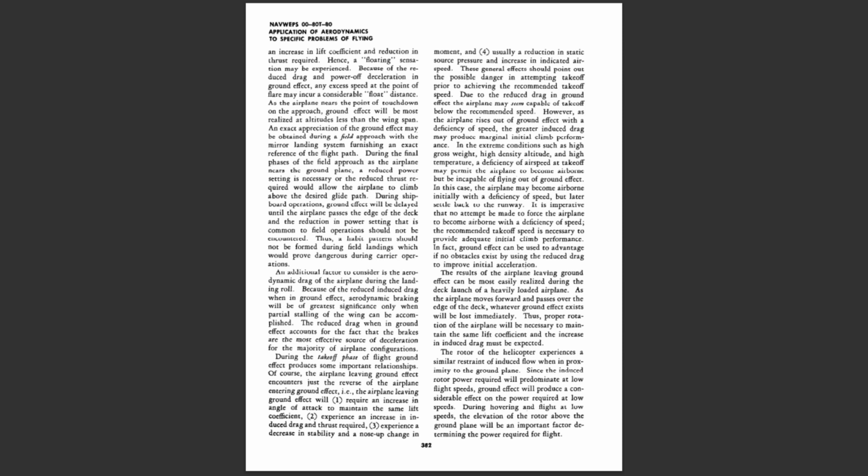During the takeoff phase of flight, ground effect produces some important relationships. Of course, the airplane leaving ground effect encounters just the reverse of the airplane entering ground effect, i.e., the airplane leaving ground effect will, 1. Require an increase in angle of attack to maintain the same lift coefficient, 2. Experience an increase in induced drag and thrust required, 3. Experience a decrease in stability and a nose-up change in moment, and 4. Usually experience a reduction in static source pressure and an increase in indicated airspeed.